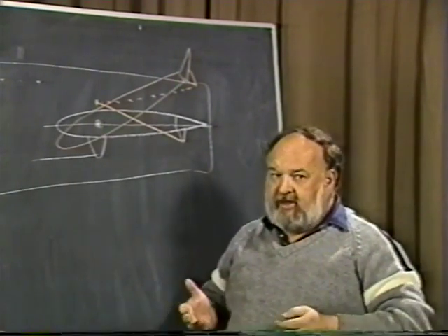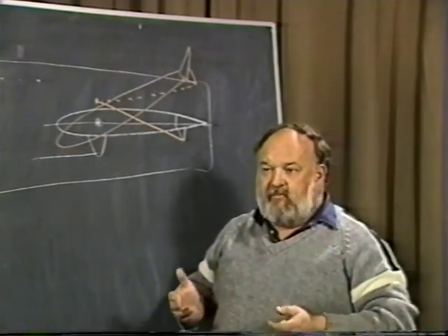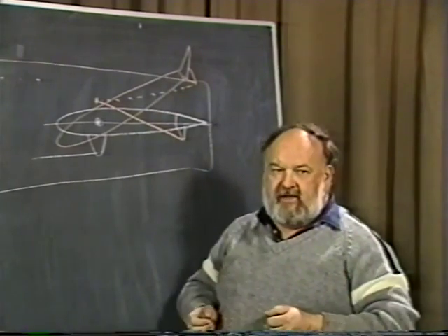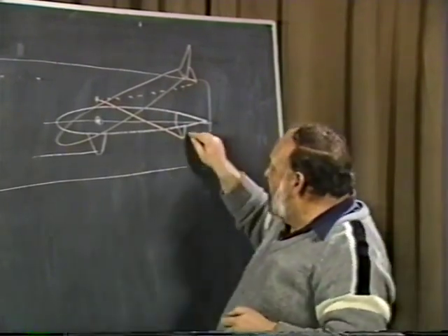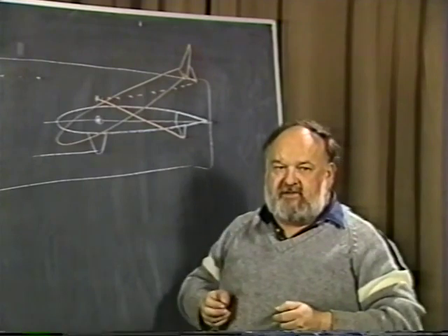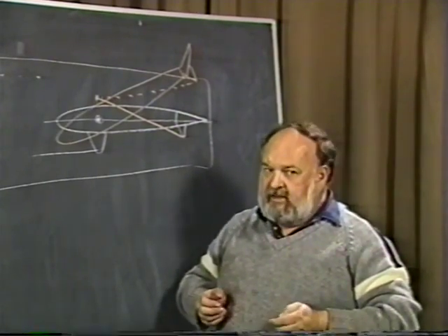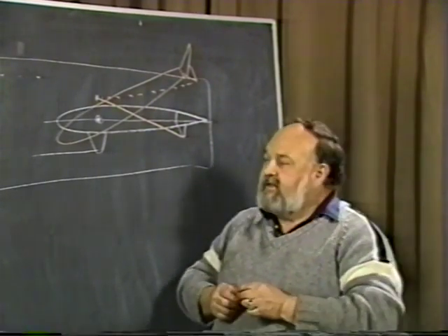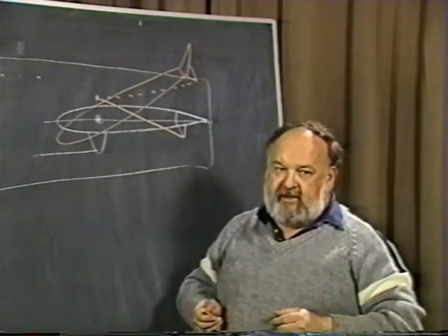And you can actually build the airplane and get it flying, and once you're flying, you say, wow, the elevator is too heavy. No problem at all. You go back there, almost drill different holes, and you can find new positions on your linkage and linkage alone and dial in the kind of stick force you want. This is the real nice part about an all-flying tail.